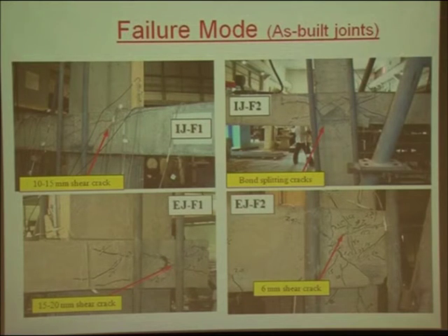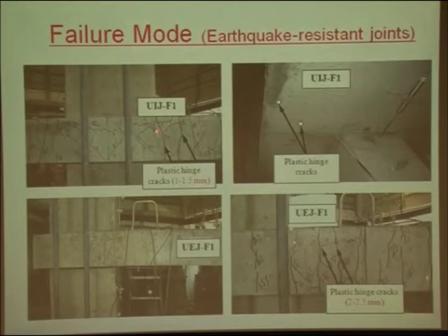The results for the existing joints are not good, please note, but when we repair them for earthquake, when we strengthen them for earthquake, we provided some reinforcement at a very low cost, with very little labor, and without changing our structural system. It is very easy to make our buildings much stronger against earthquake. You see the cracks, there are cracks. We cannot avoid or escape cracking in the structure. But again, they performed excellently with very little effort, money and cost.